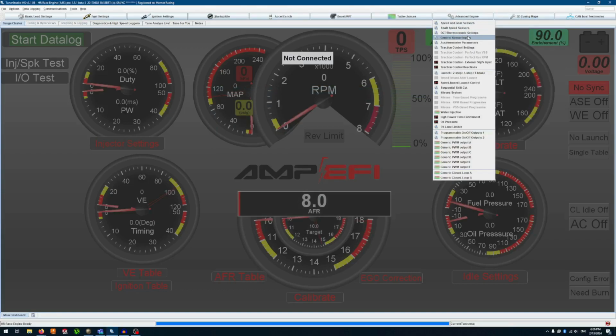And if you really wanted to, you could use fuel pressure and oil pressure to make safety things where you shut the engine off, or whatever. If your oil pressure is too low, you can shut the engine off. That is if you trust your oil pressure sensor, which I usually don't. And then fuel pressure sensor, you can do some weird stuff with your fuel pressure sensors. I don't recommend it because it's really complicated and you don't get much benefit, but you can.